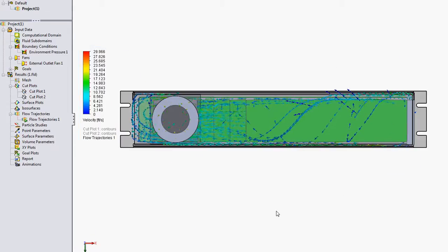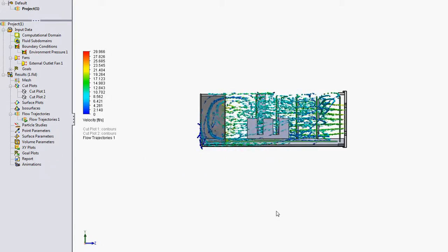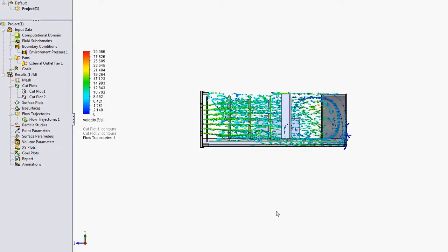So that's one of the other things to be cognizant of in this design. As you get good airflow over the front here, I would keep any high dissipation components out of this back area, just kind of notionally. My thought was I know where my heat loading is up here, and back here I'm going to be holding off on putting anything that's going to be a high power dissipator, or if I do, I'm going to have to redirect some airflow back there.